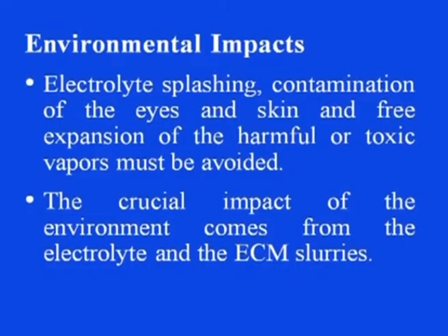Environmental impacts: electrolyte splashing, contamination of the eyes and skin, and free expansion of the harmful or toxic vapors must be avoided. The crucial impact on the environment comes from the electrolyte and the ECM slurries. Most of the time, sodium nitrate fulfills the requirement of high removal rate and surface quality.